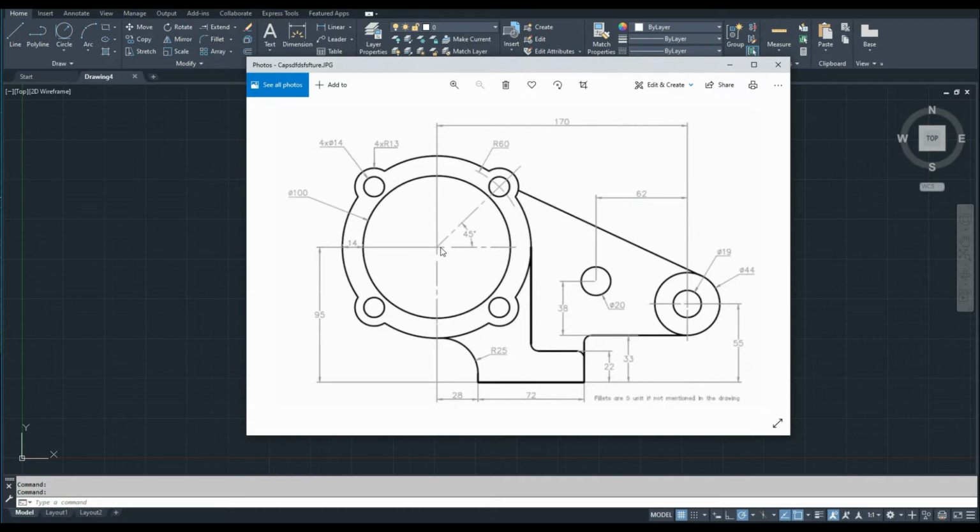It should use its own layers. Mechanical design, plumbing, electrical design, network design, anything should have its own layers. Each layer, for example, for electrical switches, for electrical lights. So we can keep one layer for each item.